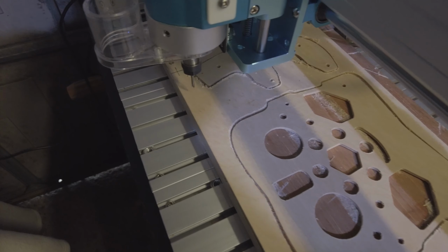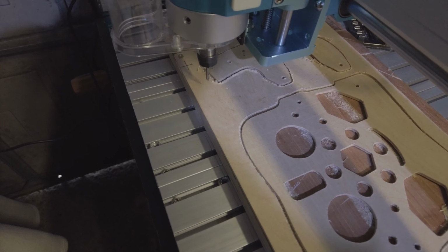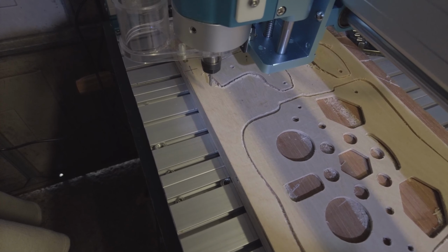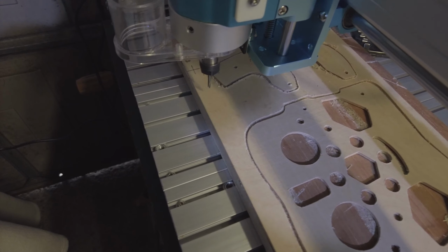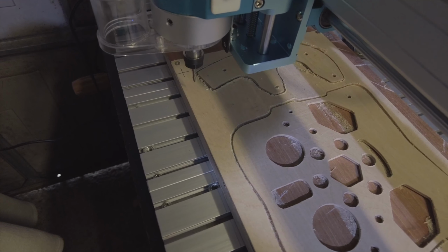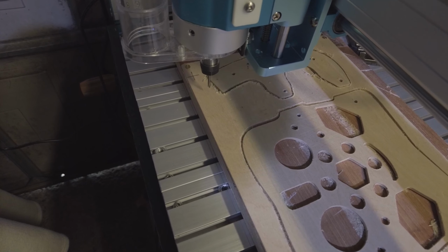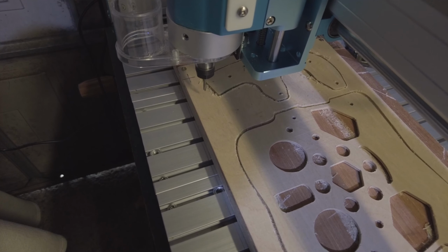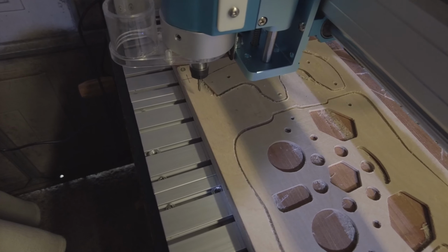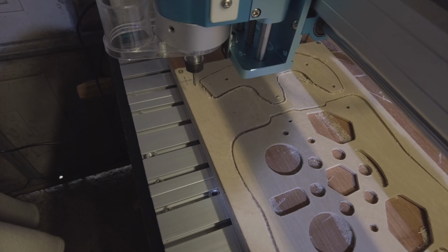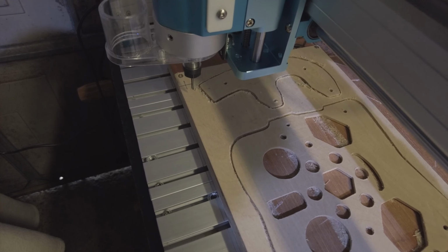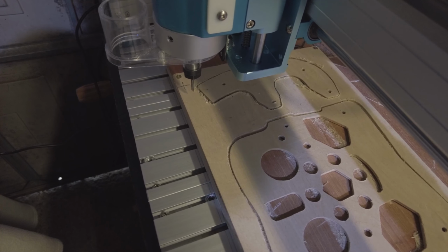So it's pretty simple to just do a cutter change, but you must remember to zero off. That will change when you zero off with another cutter, but that doesn't make any difference because you're zeroing off to the point of the G-code.